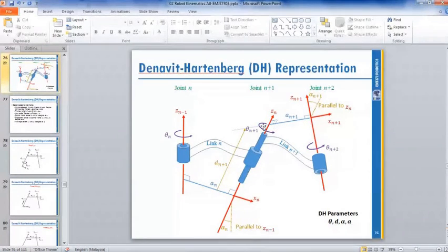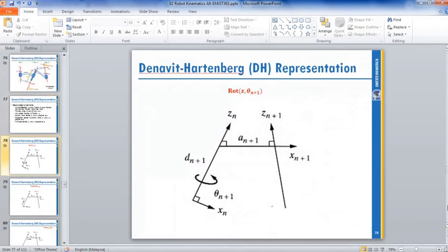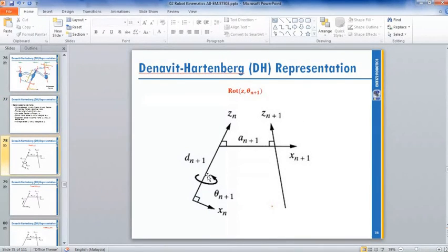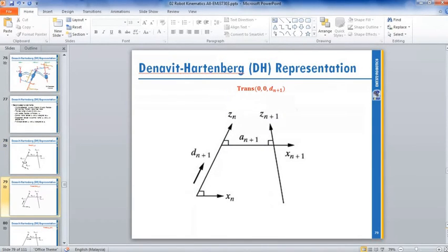This is because of your robotic arm. You design your robotic arm bending 90 degree, for example, or you have an angle of 90 degree, the fixed angle. For example, this one. So you rotate Z, that means theta. Rotate Z, so you apply a Z rotation matrix. And then you have translation Z, D. So that means you have a translation matrix on Z.